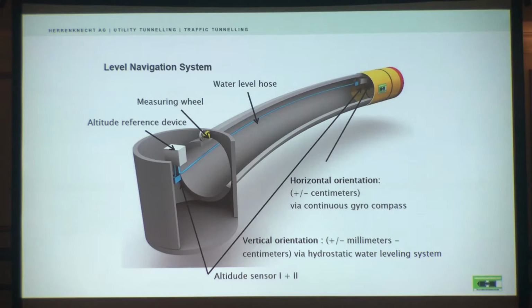Curve drives. Okay. Curve drives you can do. As a rule of thumb, do not go designing pipes which are 2.5 metres long in this country with a 1 degree angle of deflection. You will break them. I know you can do it, but the problem is, as Jim and Graham both illuminated, you will have a wobble on your pipe jack. Nobody steers it perfectly online. And those wobbles will exacerbate whatever you put in as a curve.